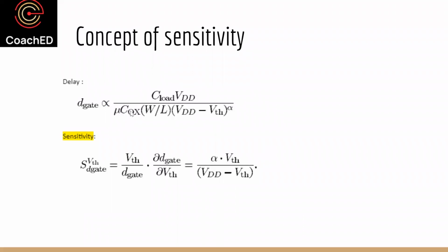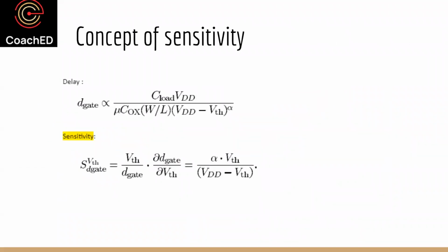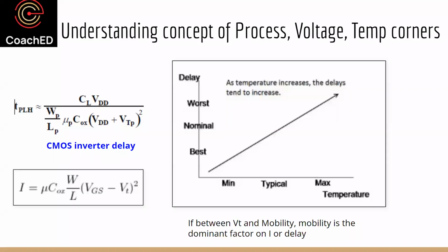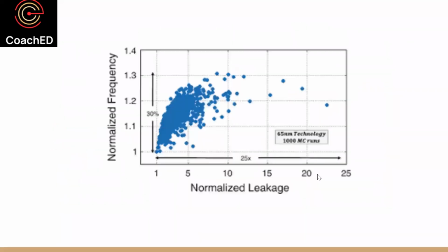So first you need to build an intuition, a good mental model, which some of these equations give you. And you can do a quick analysis. And then you can say, okay, this circuit will work or not work. And then once you've decided on the circuit, you have to go back and run a full simulation. Probably you'll build a layout, you will extract it, which means all the parameters that are in the layout show up in the extraction. And then you run a full simulation across various process corners, fast, typical, slow, and so on, across different temperatures, and you can see the effect of that. That usually is the full design approach. Does it answer the question?